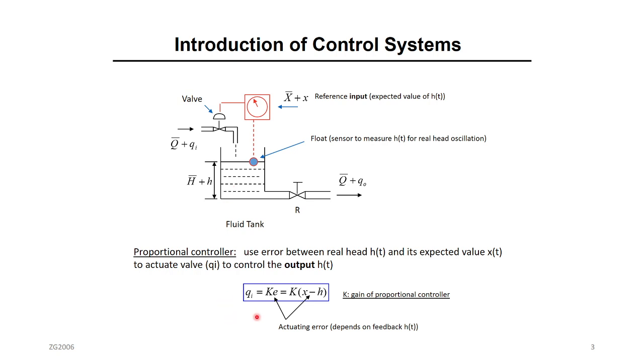All right. Now we will pick the simplest type of controller. We call it K. K is called the gain, or the proportional controller. Usually it's a positive value, like 0, 1, 2, 3, 4, 5. This is the simplest type of controller and the most common, most popular. It's similar to the volume in your car radio, for example. You see the volume 0, 1, 2, 3. This is similar to the gain here.